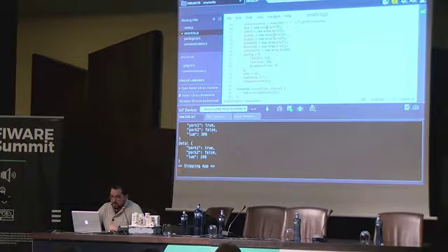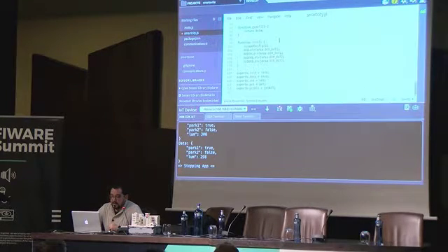As you can see, the only thing you have to do in order to read and write the data is to define the data in a new variable called GPIO in the case of the digital entries and AIO in the case of the analogic ones, and define the direction of the interaction in the case of the digital ones.